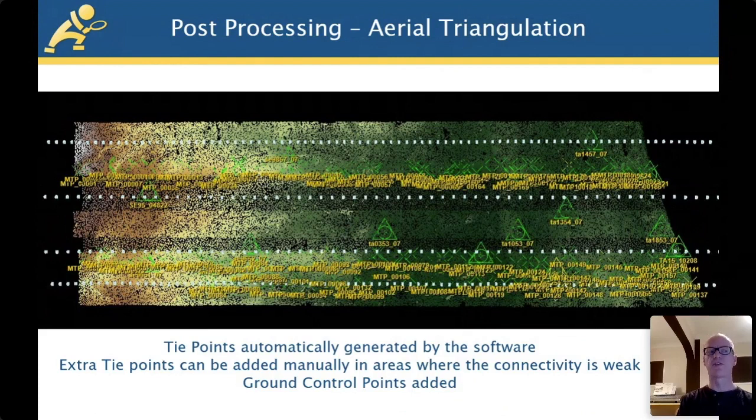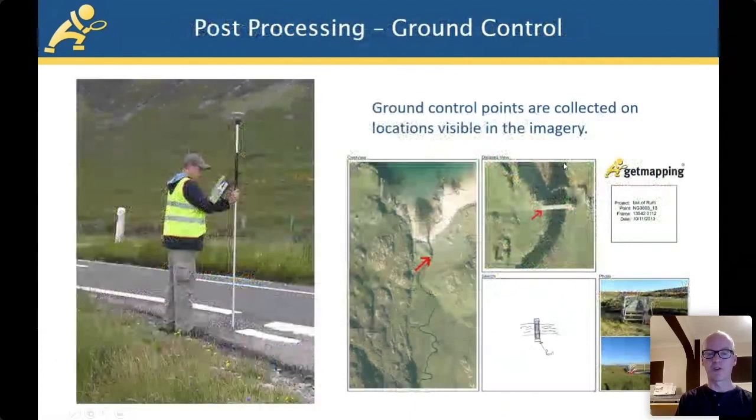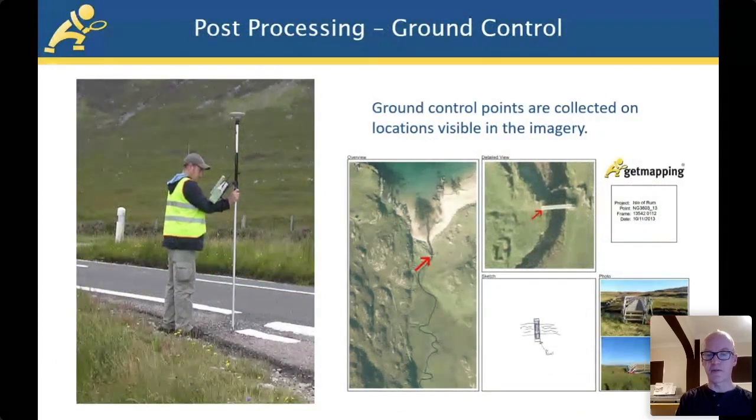And then on top of that, we introduce ground control points, which are the green triangles in this highly complex diagram. Now, control points are known points on the ground. So we take GPS survey equipment and we survey features that you can see in the photography, typically things like road markings, manhole covers, and we can measure those to a 1 to 2 centimeter accuracy.